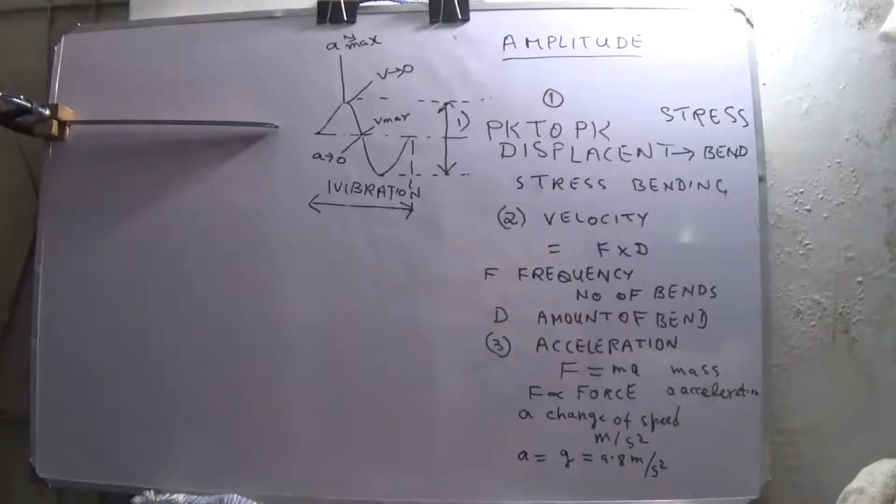The frequency depends upon the fault in the machine. Different faults have different vibration frequencies because of machine configuration, geometry, and the type of force acting on the machine, and this type of force depends upon the fault.